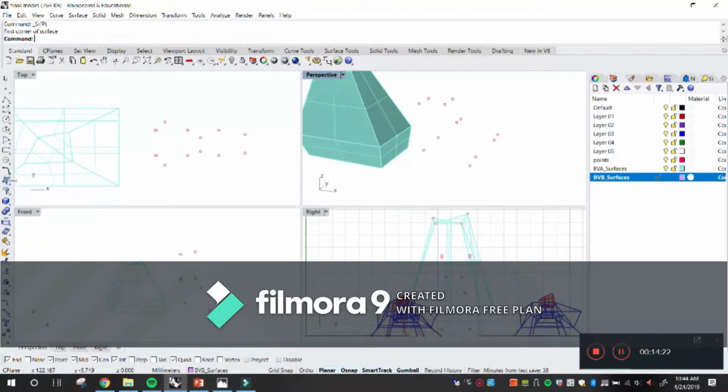I don't know if you guys have noticed, but notice my cursor right now is on the icon. Watch what's going to happen when I click on the icon to my command line. All right, it tells me the command, and that's a way that you can start learning the shortcuts for any command, any icon, or any action that you perform in Rhino. It tells you right here without the underscore. You don't have to insert the underscore, but for example, we know that SRFPT is the shortcut for surface from 3 or 4 points.